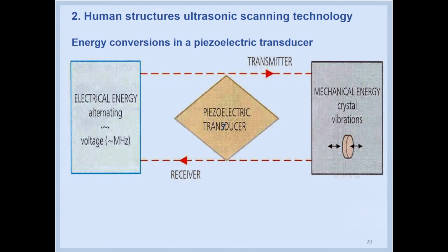The ultrasound generator is a device that basically consists of a sine oscillator and a transducer. The sine oscillator generates high frequency, more than 20,000 Hz electric power, while the transducer unit converts the electric oscillations into mechanical ones.